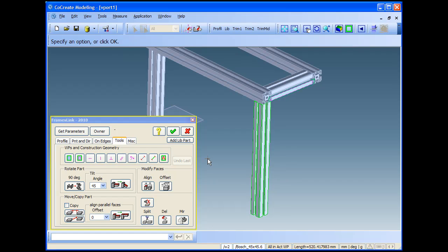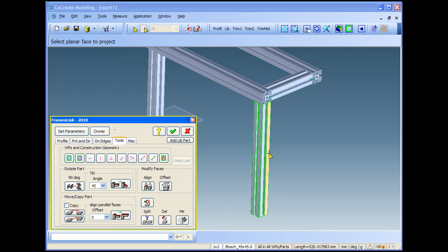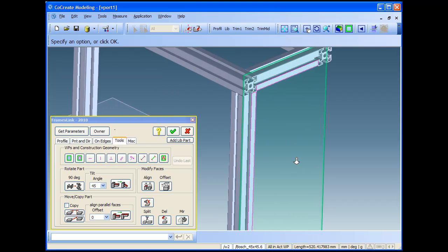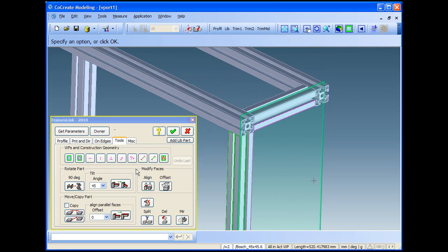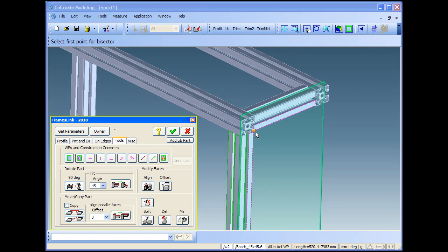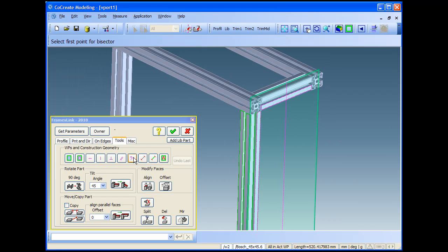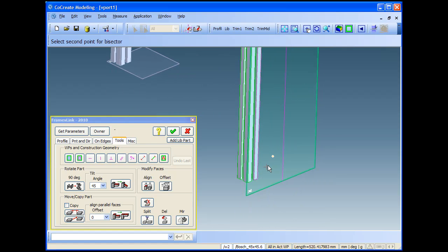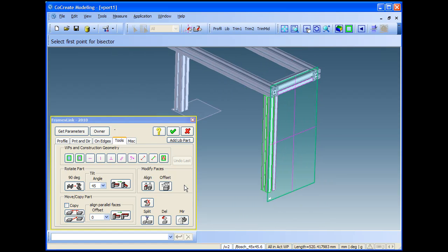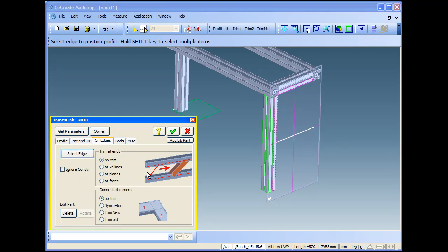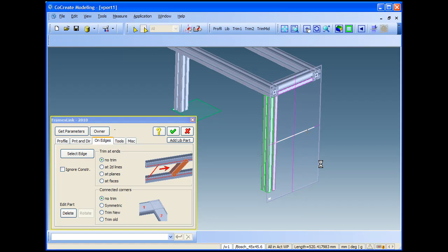Okay, we also have some construction geometry and work planes inside, and this gives users the chance to do certain construction geometry without leaving the menu. Otherwise, you'll have to close the menu, go back to modeling, do the construction geometry and come back. To avoid this, we have put certain modeling construction geometry commands into the dialog. The work plane which you create now is just temporary. It will be deleted automatically when you leave the program.